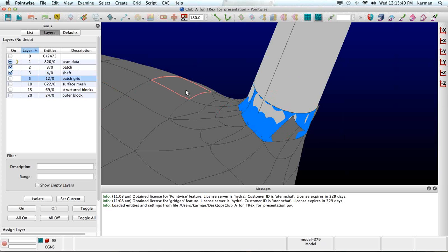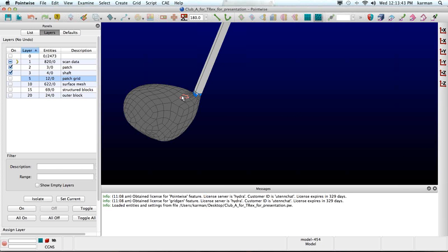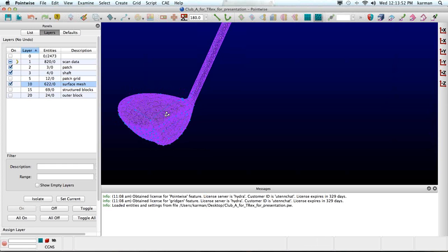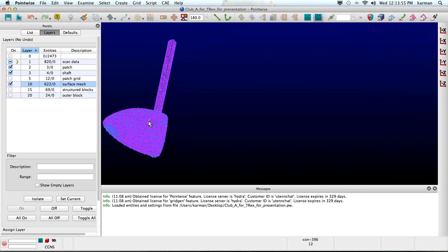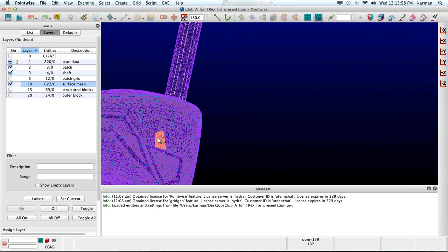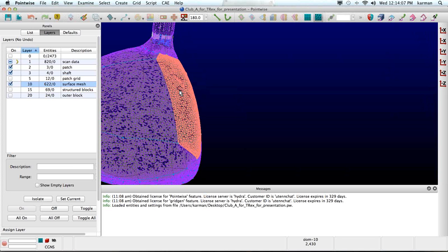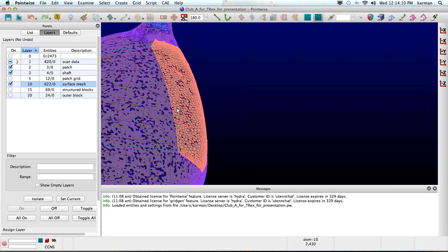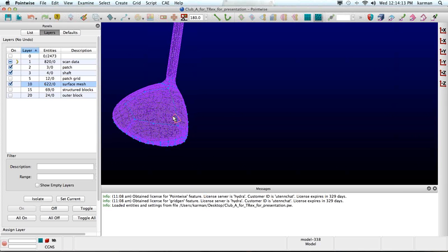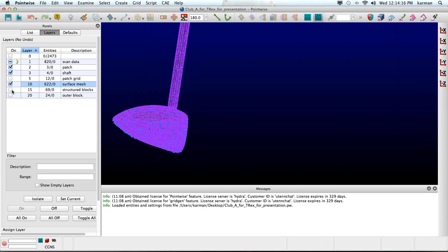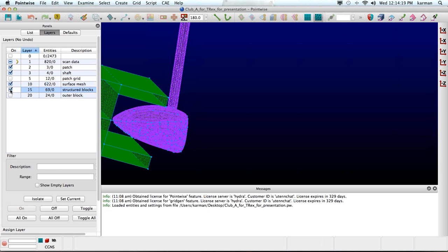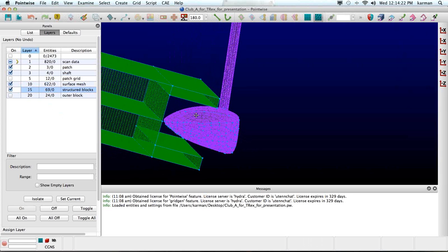And then after that, we have a complete, nice, tight geometry on which we can put a very easy, very simple surface mesh. And you can see that for the most part, I just allow Pointwise to take the patch that was read in and just mesh on those little patches. There were a few places where I got creative and decided to merge the parts of the grids together, but that really wasn't necessary. And then finally, as I said, we create the structured blocks. Again, those are to capture some vorticity.